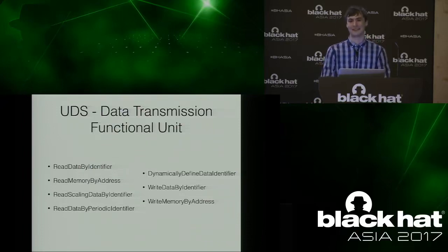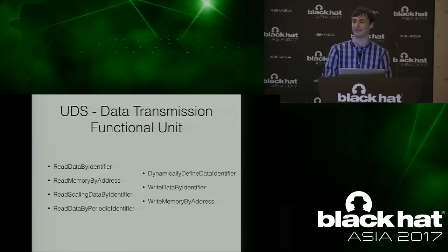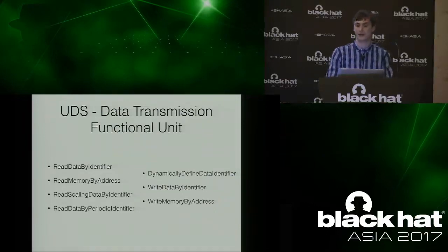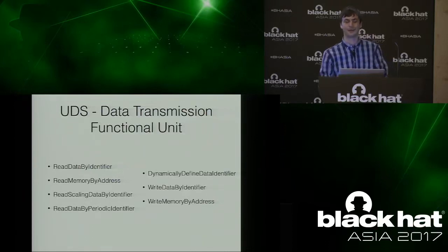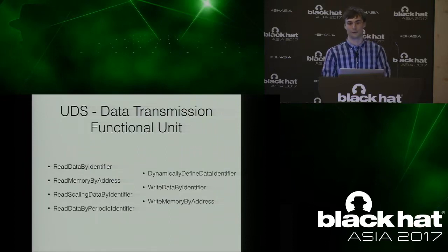There's also read and write memory by address. And that should sound concerning immediately, because being able to access arbitrary memory addresses is not going to be very safe. This is hopefully not enabled in production. I have seen at least read memory by address enabled on controllers. I am a little scared to try writing memory by address because you can see if the service is enabled, but you can cause some really bad things to happen if you just overwrite random memory in your airbag controller. You might blow the airbags. That is a thing that could happen. So those ones are scary and hopefully aren't enabled.